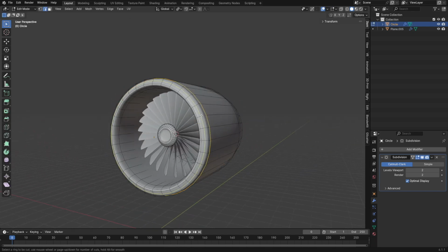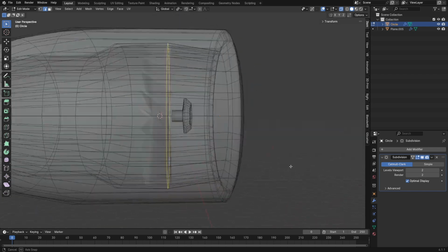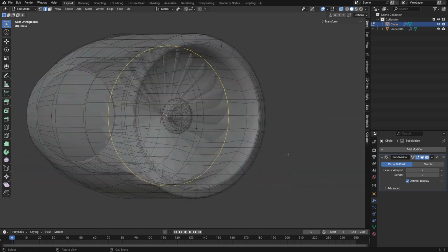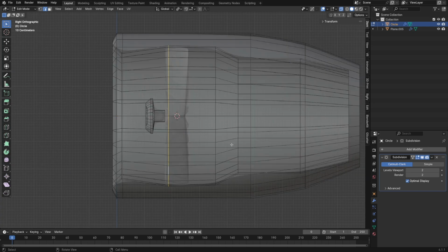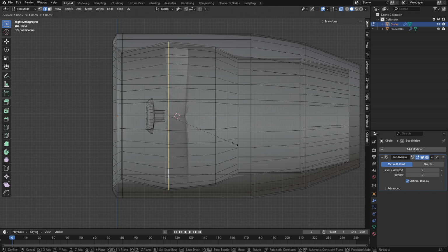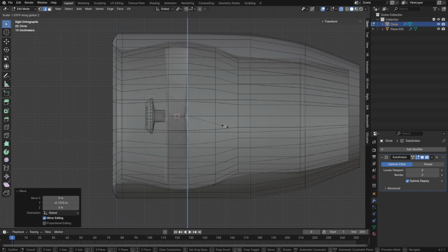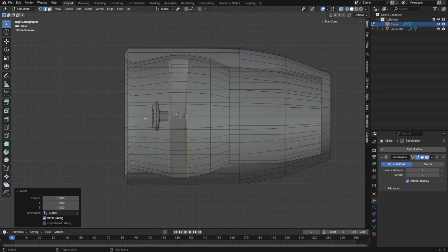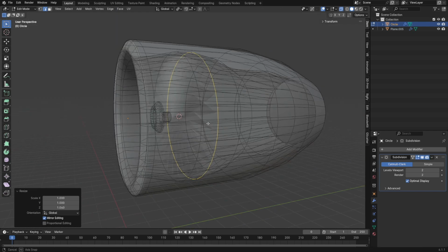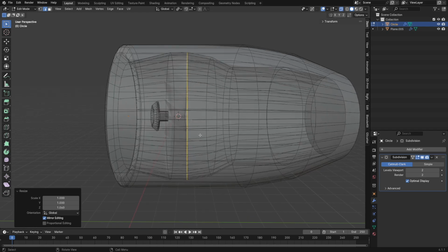And from here, essentially, you can continue to sharpen off the edges, but inside where the propellers lay. Now, if you find that inside needs to be expanded, add a loop cut and expand it. That way, the propellers have space within the object to rotate without interfering with the other objects. I hope this makes sense in a way.